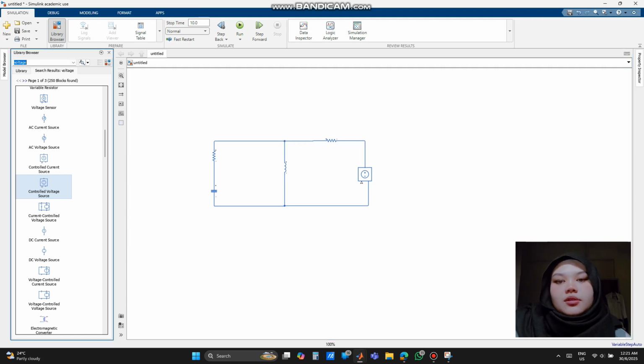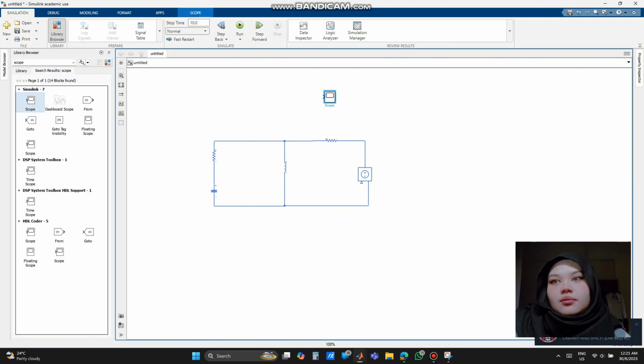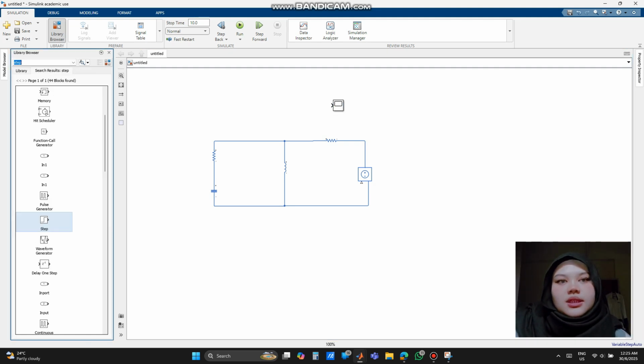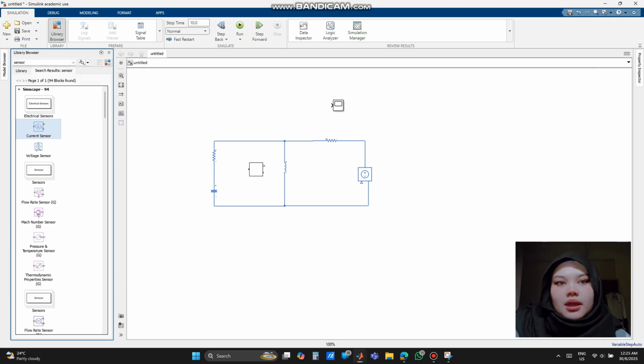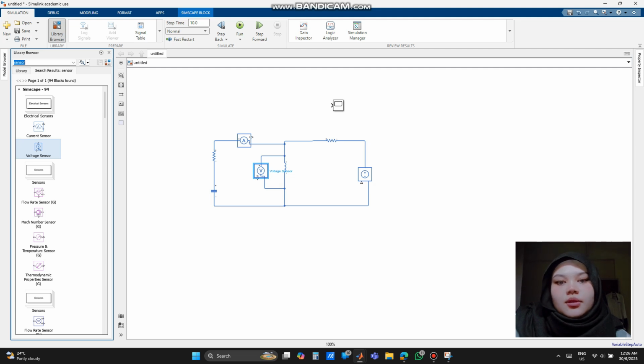It has a normal voltage source, but in Simulink MATLAB we use a controlled voltage source because this block converts a Simulink signal into a physical voltage in Simscape. It allowed us to apply a custom voltage input to the RLC network, so it can display on the scope, which is used to visualize how current and voltage change over time during the simulation.